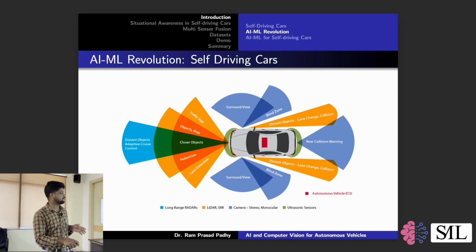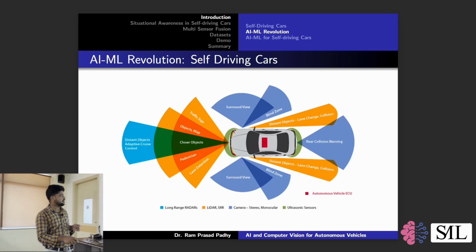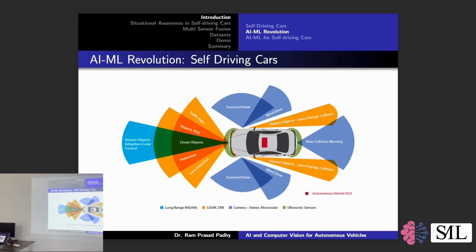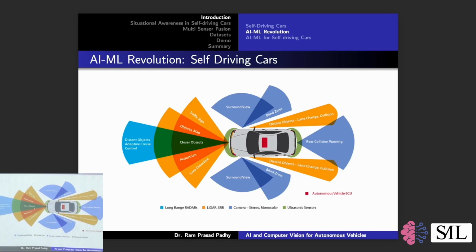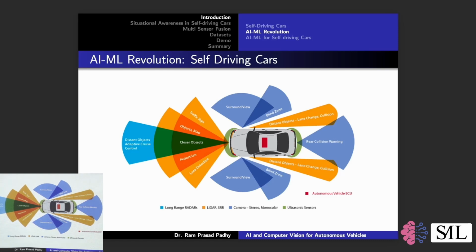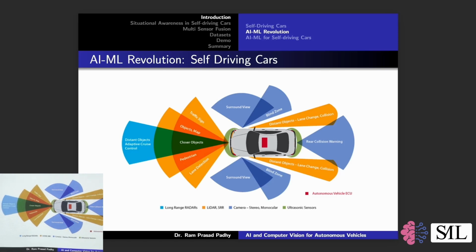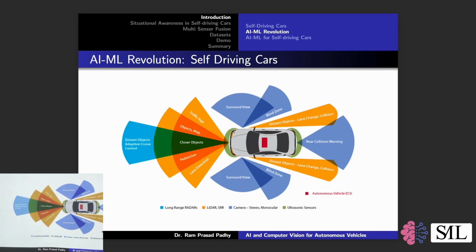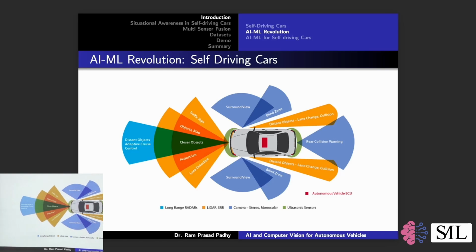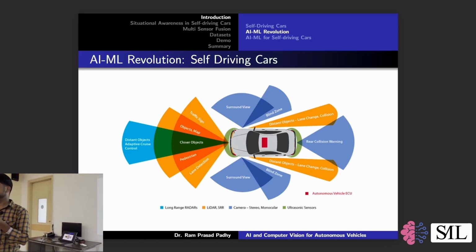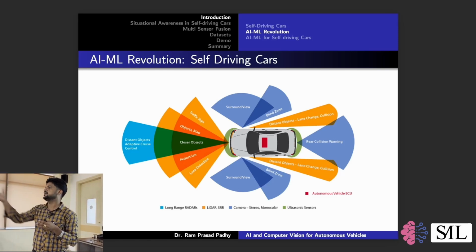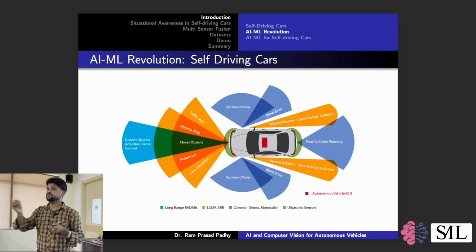So these are the workings of different sensors. If you think about a camera, generally it is used to find objects in the near vicinity, like pedestrians, bicyclists, cars, trucks and vans. But this camera sensor can only detect in the 2D plane. Those who know image processing would know that with a camera we just get 2D data. We don't get the actual depth. And when it comes to a self-driving car, we actually need 3D, right? Everything is in 3D.